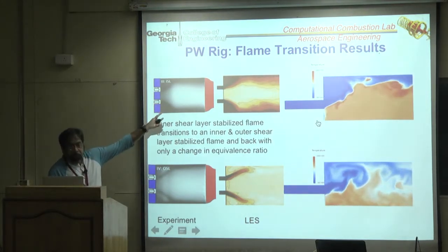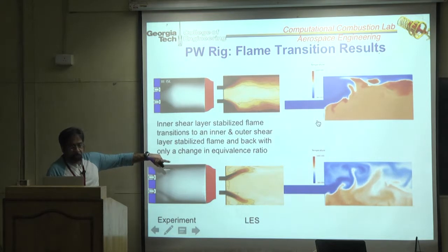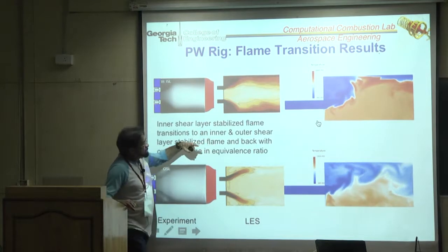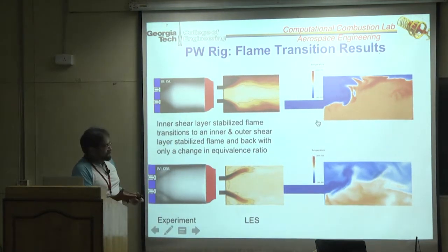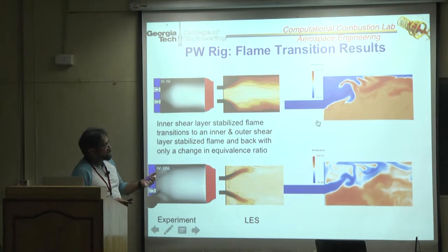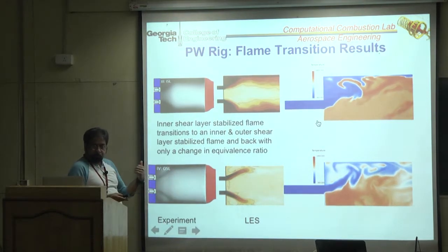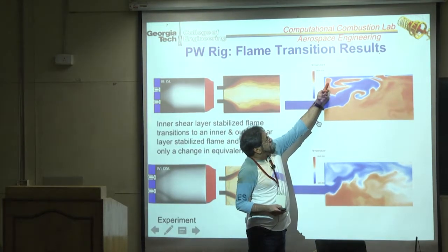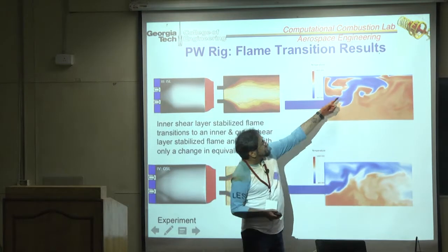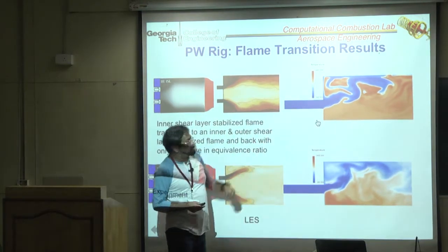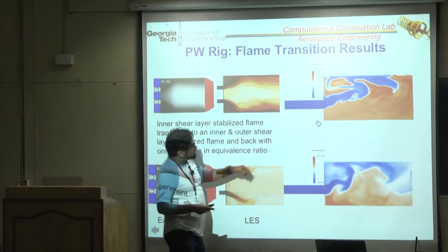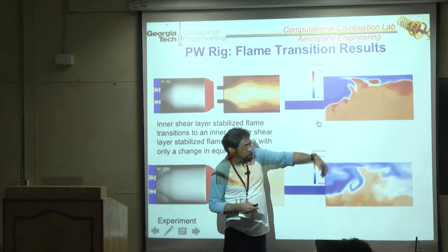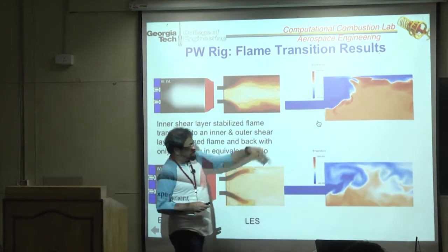Well, the wall temperature is also included because the wall did change temperature. It's an isothermal wall. The wall temperature was measured. But it was a combination of both because, if you think about it, when the equivalence ratio is high, flame speed is high, so it wants to come back in, and when the wall is hot, it can light up. This is not igniting. It is a flow. The flow is picking up some features and bringing it around. And when it becomes lean, then it becomes too weak to come up. So even though the wall is hot, in both cases walls are hot, measured temperatures.